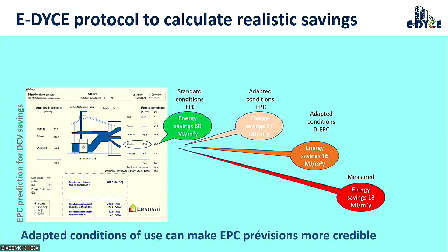And you see also the power of passing from the yearly mean of the ventilation rate, instead of 0.7 of yearly mean, you take day and night. As during the night you have a lower external temperature, of course, if you stop ventilation during the night, you have all these catastrophic CO2 indoor environment quality problems.